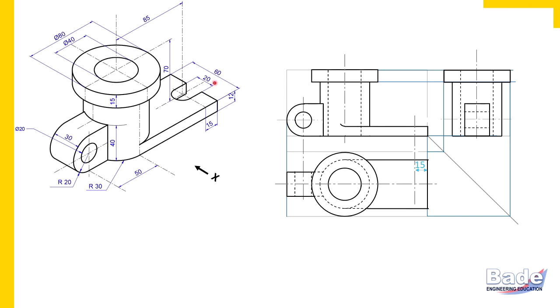So here the diameter of that semicircle is 20 millimeters. So use radius 10 millimeters, watch here, and complete that semicircle. Now to complete the U shape, from the ends of this semicircle, draw edges parallel to the length, watch here. And this is how the U shape opening is complete, but it is not a hole, it is a slot.